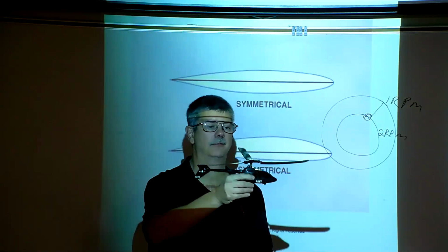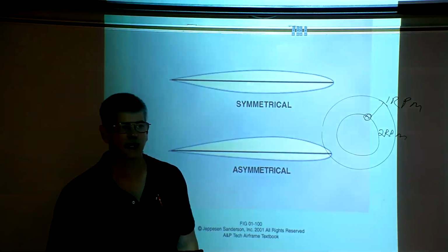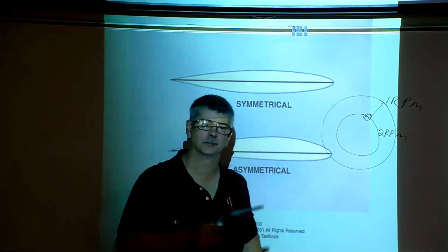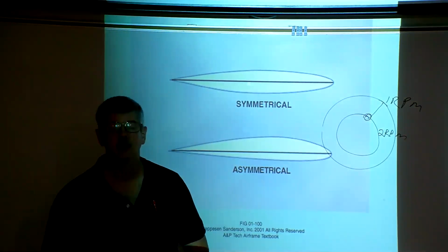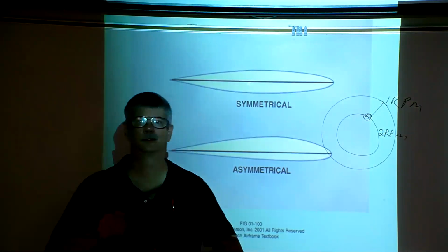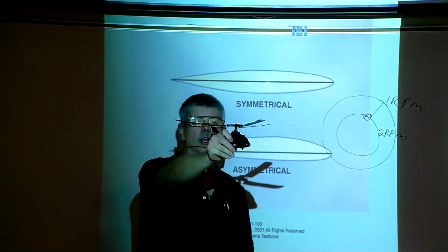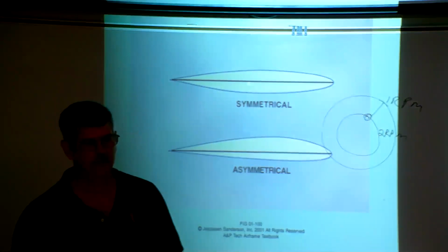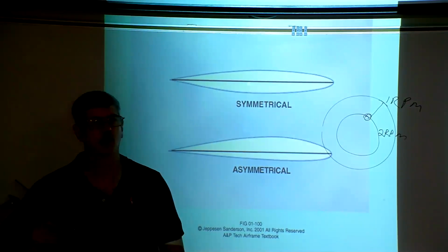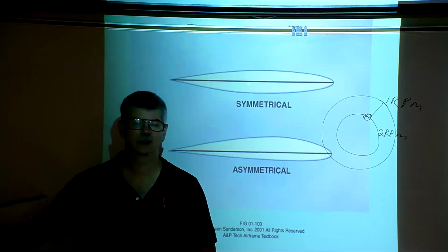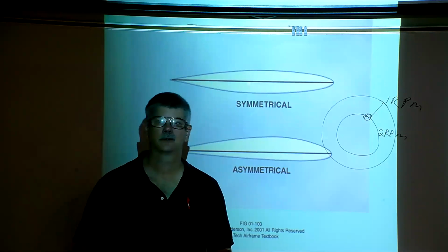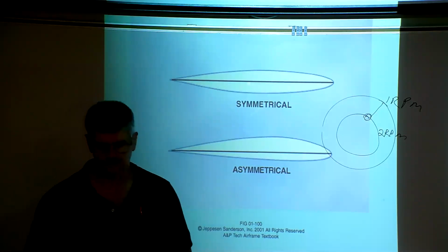As we fly forward, the vertical velocity has decreased because we've increased the horizontal speed of the aircraft. This then increases the angle of attack, where now, as long as we're moving forward, we can carry that weight even when we're in or out of ground effect. We can't stop, we can't hover out of ground effect with the extra weight.